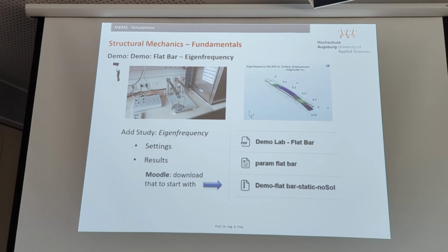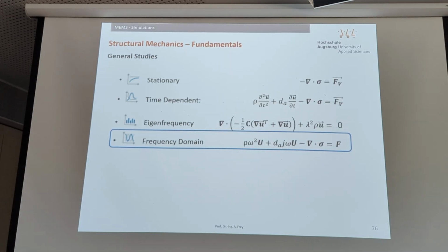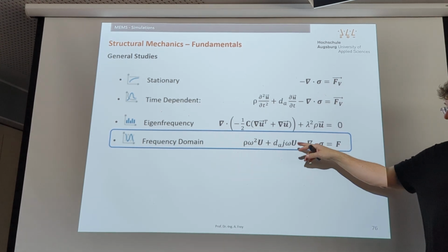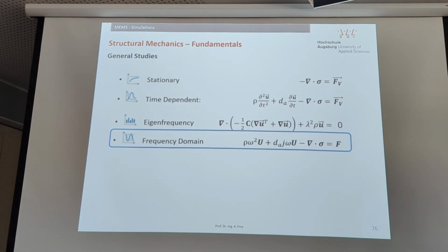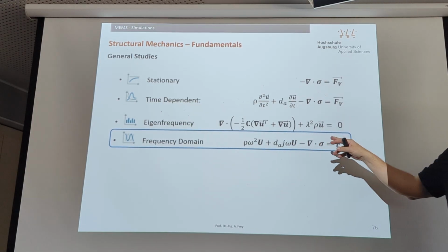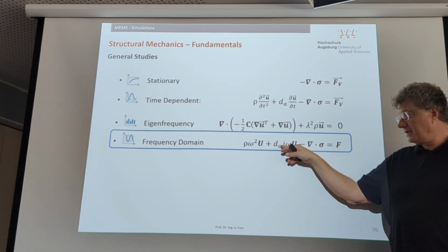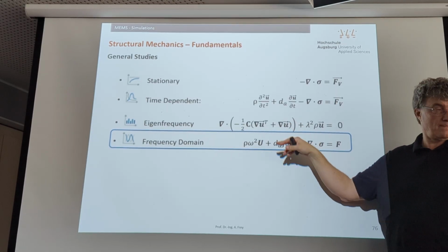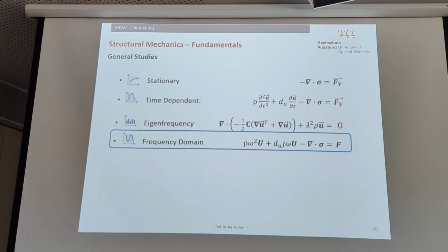So that was this demo, eigenfrequency analysis, and for the last one, I didn't prepare a demo, but I already mentioned if you would be interested in the amplitudes, you would have to run a frequency domain analysis, which would give you the amplitude and phase over frequency, such a Bode diagram analysis. So that is much more numerically expensive, so it's a much more complicated simulation than this one. So you have to decide what you need. If you only need the frequencies, it's a good idea just to use the eigenfrequency analysis.